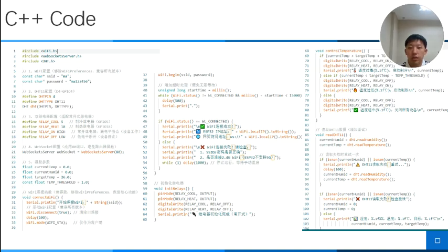Connecting to the cloud platform. The platform is specially designed for IoT devices, supporting device access, data transmission, and command issuance. We realize the stable connection between the ESP32 and the cloud by configuring the client ID, token, and the app ID,